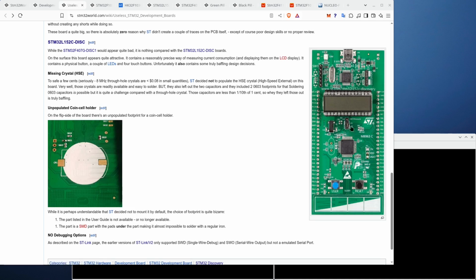It is wired up, but the same pin is being used for this gigantic display up here that requires, I don't know, 20 GPIO pins. And while there are pins that are unused on this MCU, they decided to use PB3 for the display. So SWO, it's kind of there, but it kind of doesn't work. Which is, I mean, it's insanity.